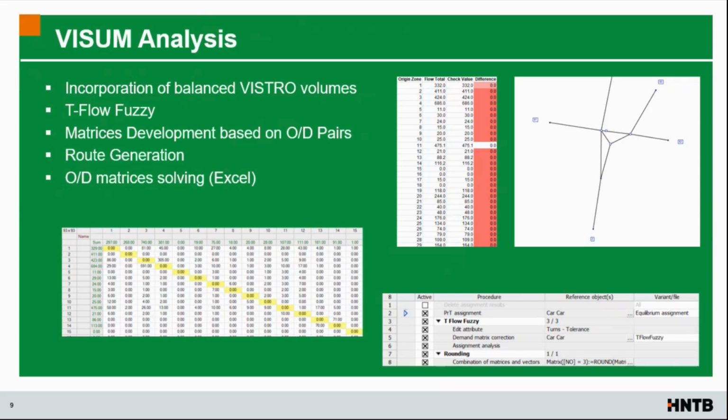We brought it into our own Excel sheet later on so that we could, with those source sinks that we had and everything, some of the origin and destination pairs were different. So we used our own Excel sheet that we created to solve and zero out everything so that if there were extra destinations or origins, we have this formula that we use to determine where those were being seen, and we could pull that out of the Vissim static routes and put it into our Excel sheet and then fix everything and add those in, put it back in, and then match the relative flows up.